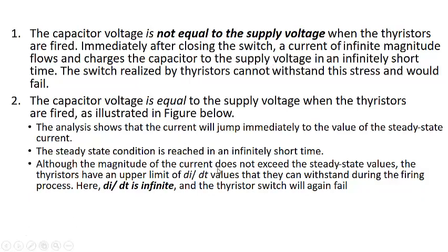Although the magnitude of that current does not exceed the steady state value, the thyristors have an upper limit of di by dt values that they can withstand during the firing process. Here di by dt is infinite. The thyristor switch again will fail, and they will be damaged.